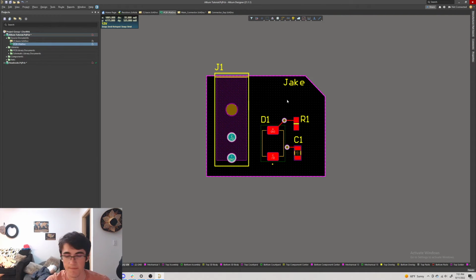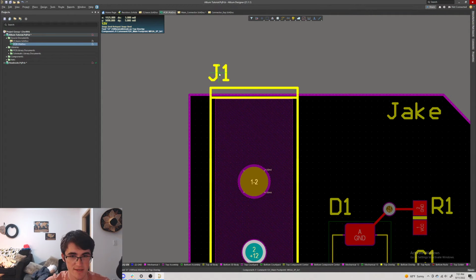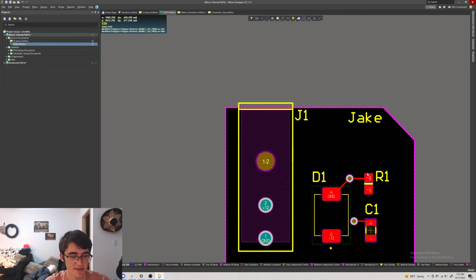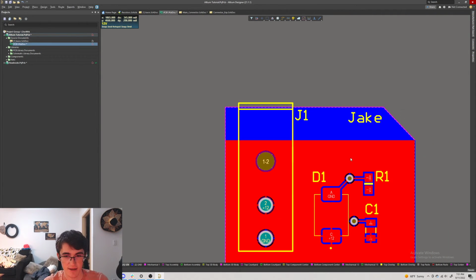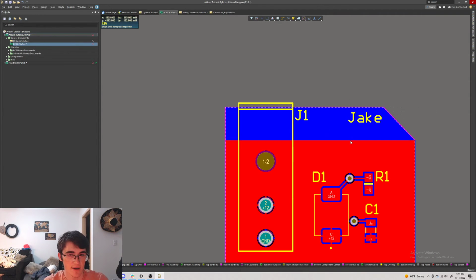But yeah, obviously it gets a lot more complicated than this, but maybe you got stuck in a certain way. One other thing to make sure is that your silk screen or your designators do not go out of the board like this. They go in. Then I'm going to save this, and then I'm going to bring back my... yeah, we can keep that there.